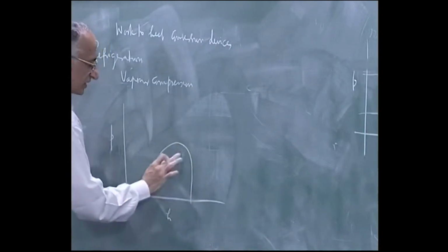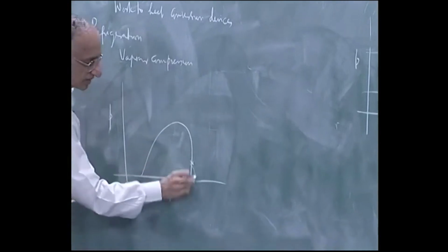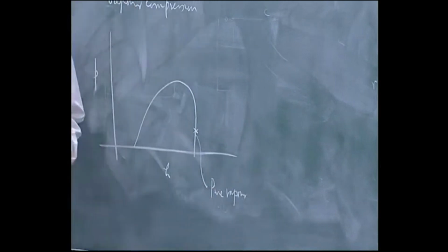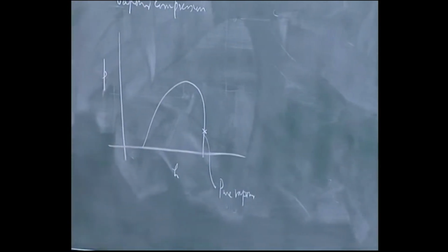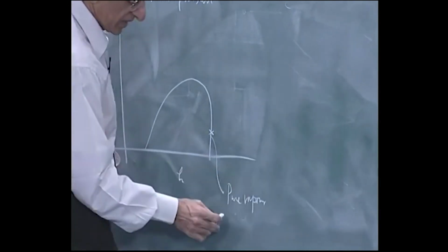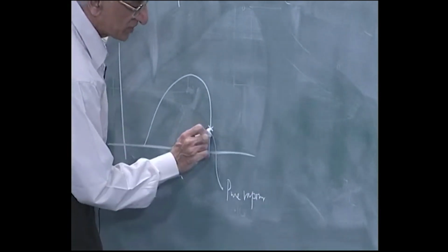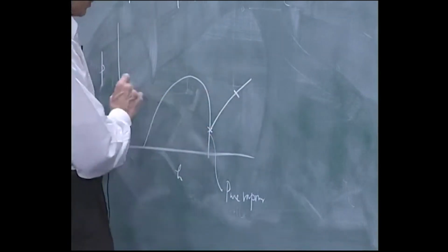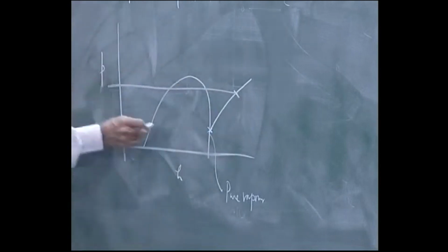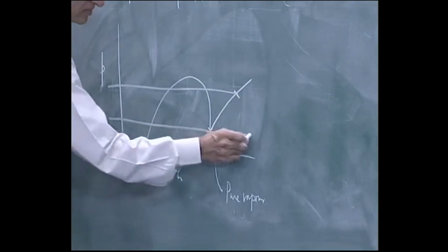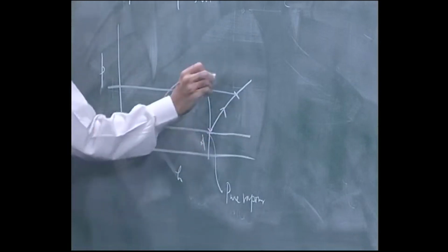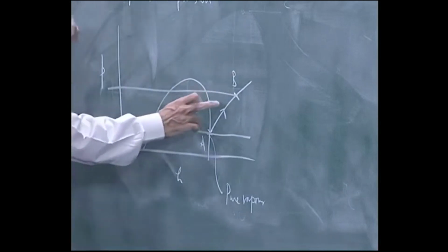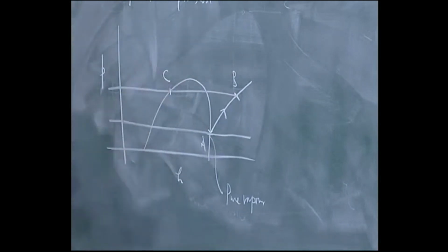Here you are talking of two phases. What you do is take, let us say, pure vapor, could be freon, now you have non fluorohydrocarbons for this, but you have pure vapor which you compress along an adiabatic. I work between two pressures, again I have A, B, this is adiabatic compression from A to B, from B I cool it to saturated liquid,